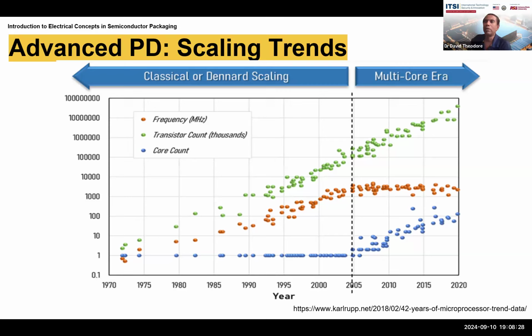And in part, we are limited by material constraints, like silicon dioxide, and so on. And in part, we are constrained by the fact that we're not able to make the devices much smaller than they already are. So we are pushing down to 1.4 nanometers, but the device physics ends up being very different in the quantum realm compared to the regular electronic device realm. So for various reasons like that, we're not able to push the frequency higher.